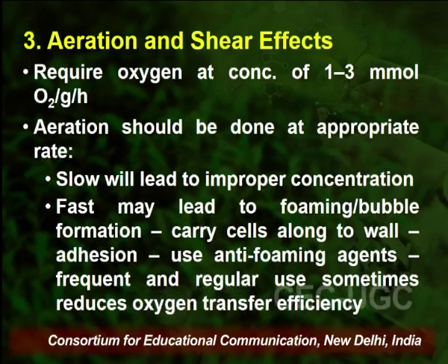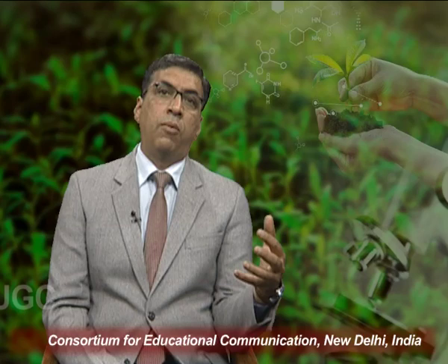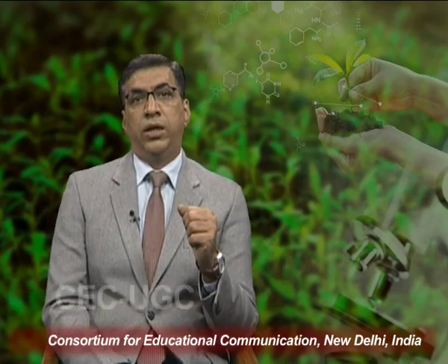Now aeration has to be done at an appropriate rate. Why? Because if the aeration is very slow, it will lead to decreased oxygen concentration in the media, and that will develop certain dead pockets in the media. That eventually will lead to improper or non-uniform growth of the media.